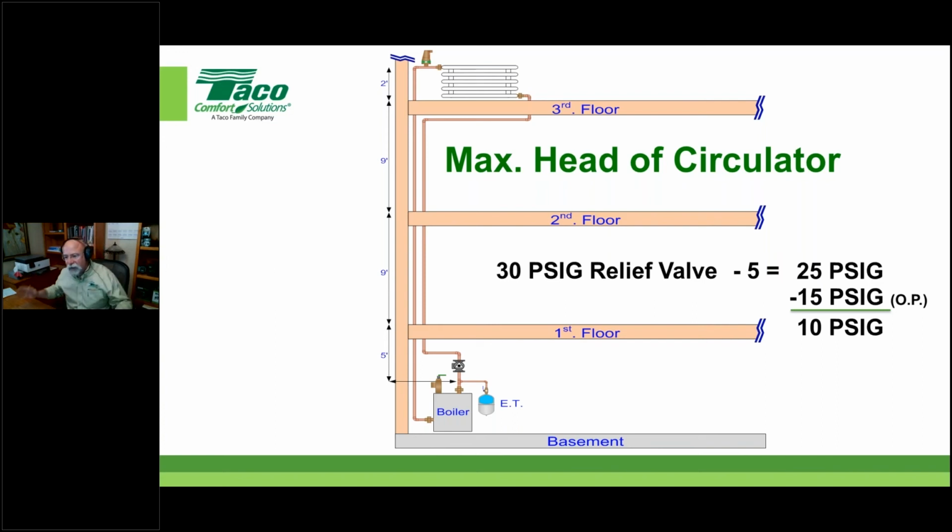It might be just set up that you're going to use, like John has talked about, hey folks, if you must do that, like they used to come packaged, those are flat curve circulators. They don't add a lot of pressure, so we're not really as concerned with this. But this is just a way of being assured that you're not going to pop that relief valve with the pump coming on and off. Okay, so this is simple.